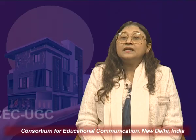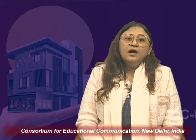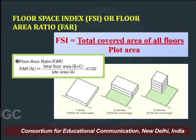So, when you are working with your design, FAR is another important quantitative value that has to be taken from the building bylaws and implemented in your design. Just to understand what FSI is, as discussed, it is the total covered area on all floors divided by the plot area, and FAR is the percentage value. So, FAR and FSI are basically related with the percentage factor.